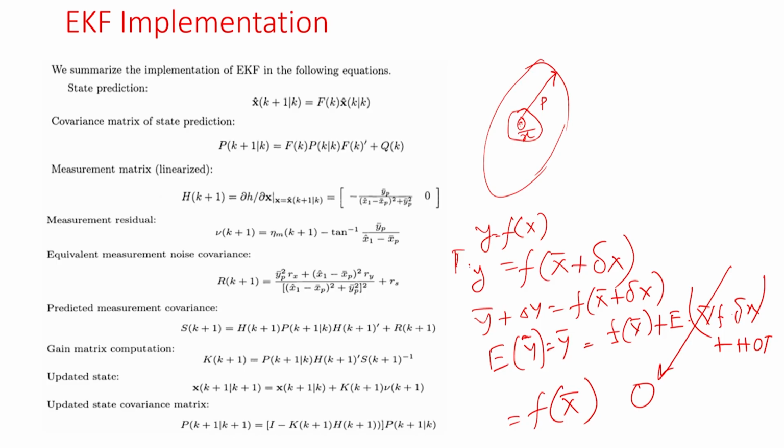When your system is unobservable or the degree of observability is low, EKF will show a problem. Even in the navigation example, when you are doing GPS IMU integration, you might see a lack of observability due to some of the IMU measurements, and at that time EKF creates a problem. At that time we use something called the linearized Kalman filter, which is not a pseudo measurement filter, but a linear Kalman filter. So, linear approximation is always better.